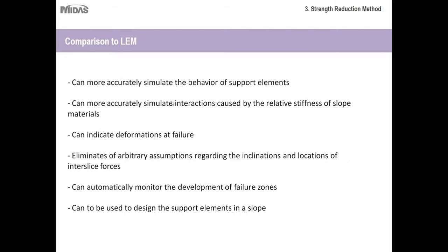that process. So instead of having a separate system to analyze the factor of safety, in other words a limit equilibrium method, and then another system or work process to do your design and having to go back and forth between the two, you can just use the strength reduction method to do the factor of safety and your design. So it's very convenient in that respect.